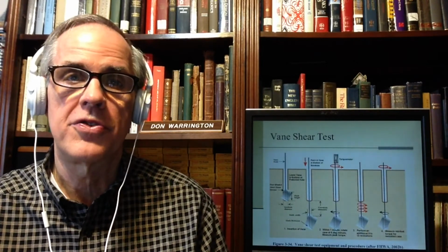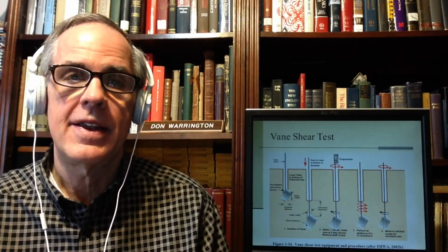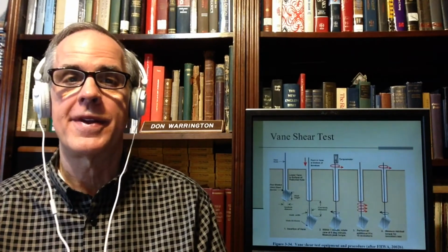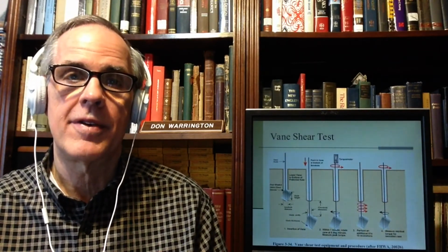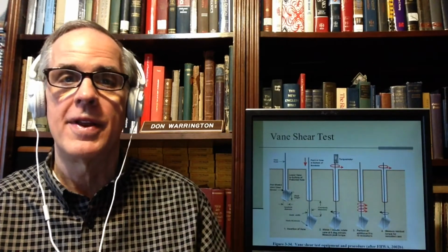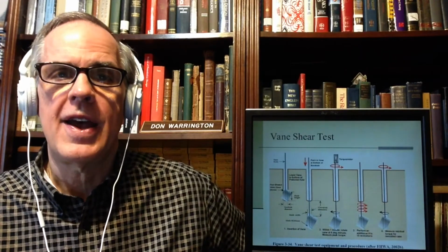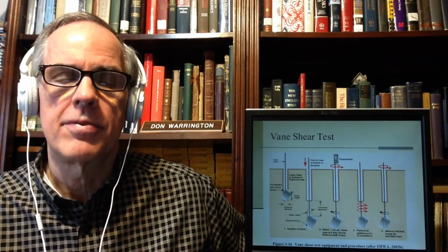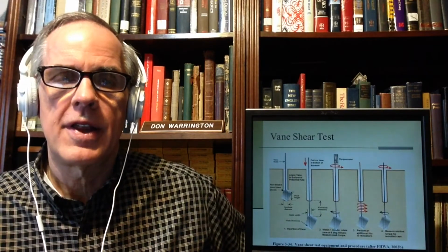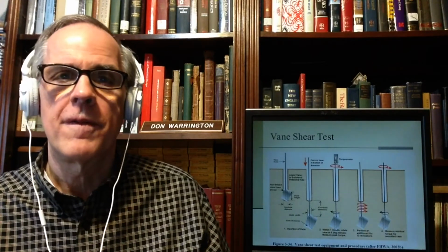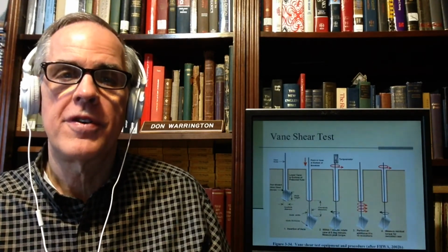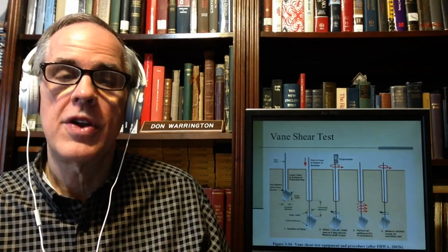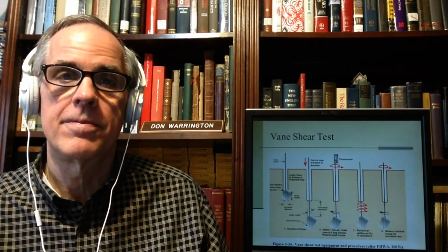That was one of the reasons why the Swedes took the lead in developing slope stability methods, because not only were they having problems just from a general geotech standpoint, but they had a lot of sensitive clays too. So the vane shear test, I am seeing more and more boring logs feature the vane shear test. We'll talk about the unconfined compression test and the triaxial, but for purely cohesive soils, if you can just determine the cohesion using the vane shear test, you're a lot better off. And I'm seeing that more often than we used to.